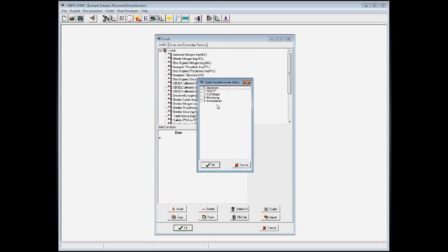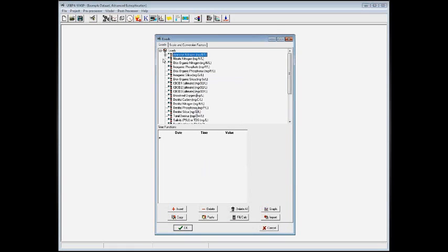And I'll say, okay, I'm going to put an ammonia load in at wastewater at segment 2 where the wastewater treatment plant is at. I'll say okay. You'll see now that there's a plus sign here. I would open this up, click on that, and you'll see that we have this time series value down here again. So we can put in time series.